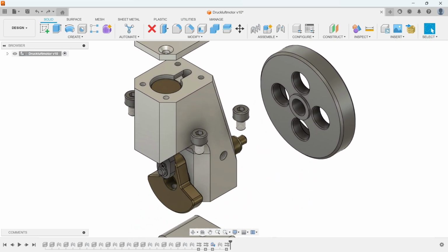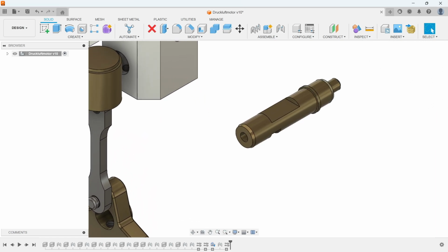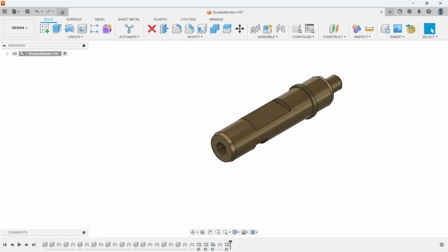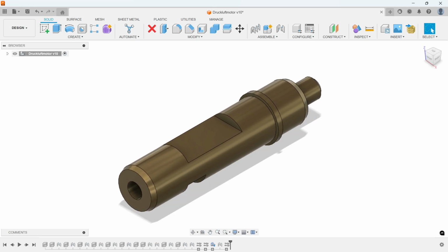Today we are focusing on the 10th component of the pneumatic motor, the crankshaft. In this video, we are constructing the crankshaft with the focus on the characteristic cutouts of this component. We will create these cutouts in two different ways. First, using the offset plane feature, and then through extrusions with offset. Along the way, we will also learn how to project geometries to enable precise and efficient constructions.